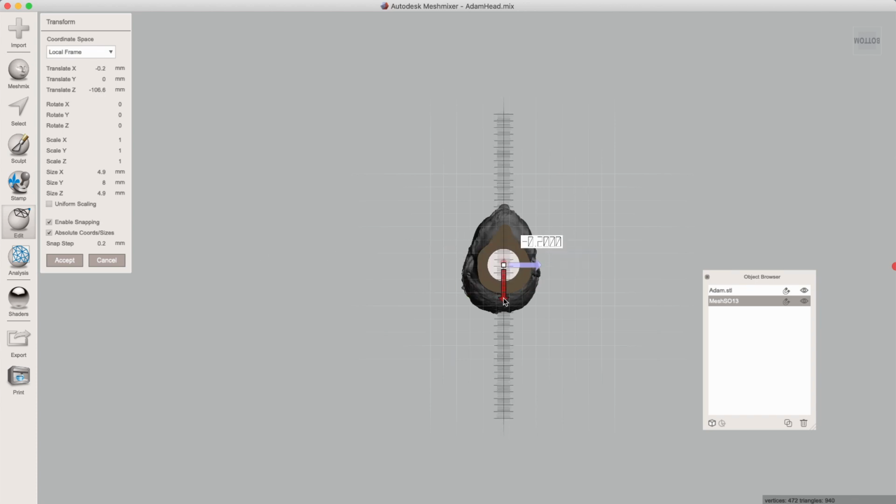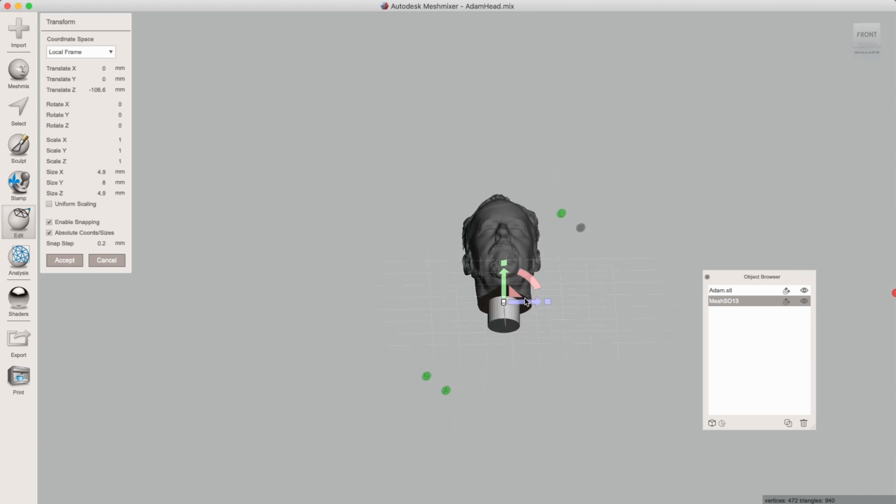And you just generally want to find that flat and place this right in about the middle so that you get wall thicknesses that you can use here. And we've got that set up. We're going to go to the front view and make sure that this pin goes in far enough. You come in all the way there, just enough so you can see a little bit of it sticking out. You definitely want some of it sticking out because it'll make the next move easier. And we're going to hit accept.